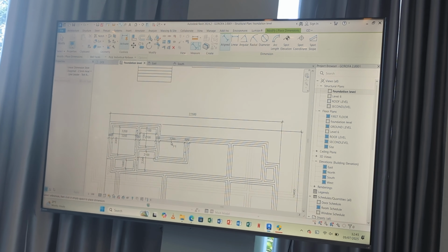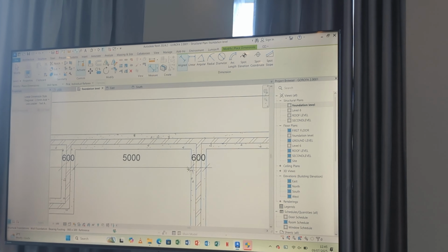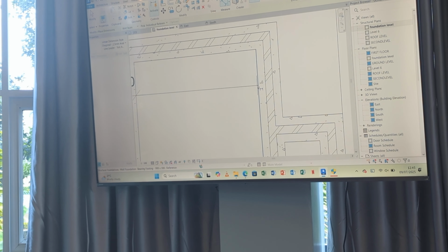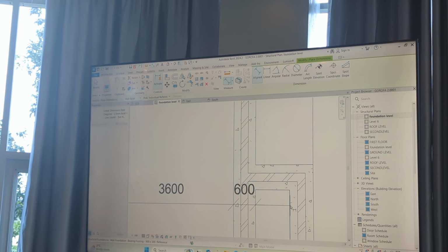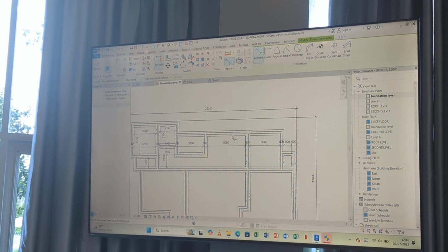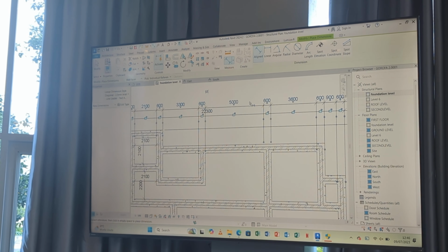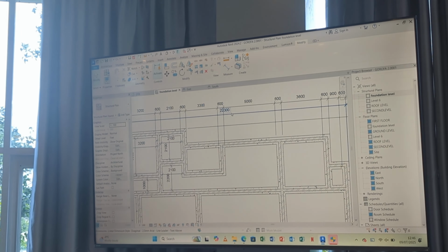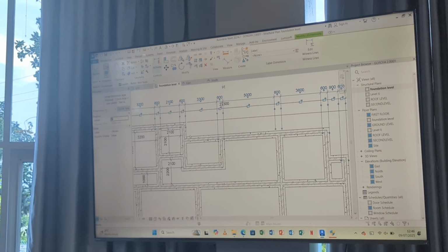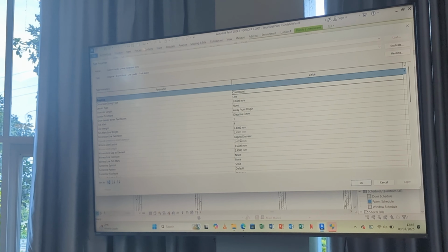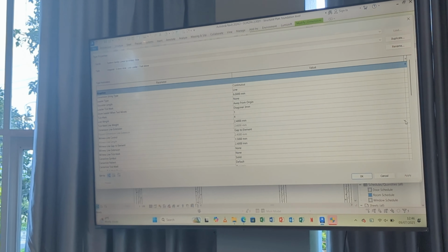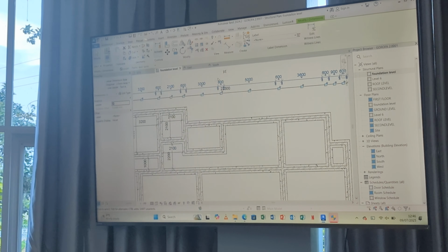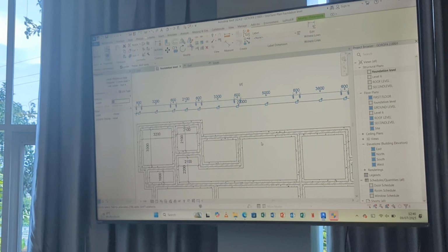Every structure you're seeing, every wall you're seeing, if I'm standing here, everything I'm seeing while I stand here, that's exactly what I pick. So once I stand there, all this is what I am able to see from this side. See that? Once again, you don't want these extension lines. Click, edit, change this extension line. On this gap to element, drop down and fix it to the dimension line. That's how you no longer have those long lines that are crowding your work.